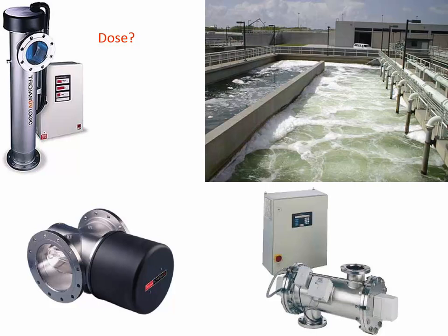Here's a picture of a chlorine contact chamber. This photo here is a plug flow reactor. Once you add the chlorine, you have to give it some time to work. And then you can see there's a stream of water where they're spraying a little bit of sodium thiosulfate here to dechlorinate. Then the water goes around the corner, and it has some time for that dechlorinating chemical to act, so that by the time the water goes to the river, it has been disinfected and dechlorinated.